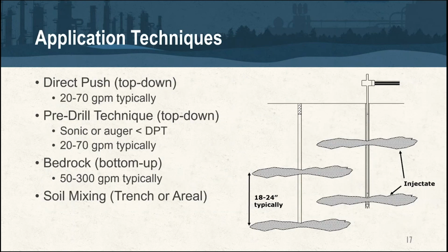So we get the application techniques. Again, this is going to be the focal point of the next webinars, but direct push, top-down progression from our standpoint is really necessary. It's an idea of the flow rates. And so this kind of gets back to the need to have an authorized installer network, because you've got to have very specific injection systems that can meet these flow rates. And those flow rates are going to vary depending on geology, depth below grade.